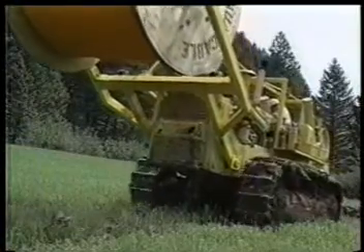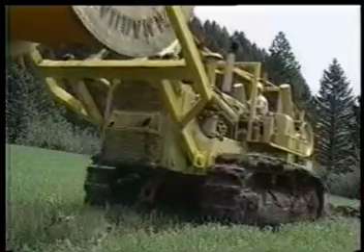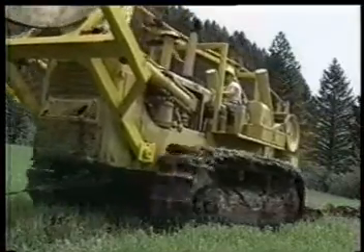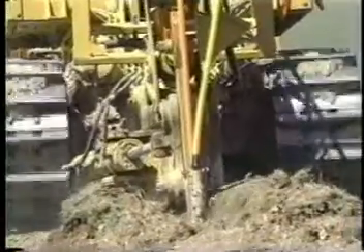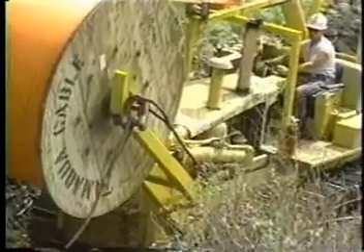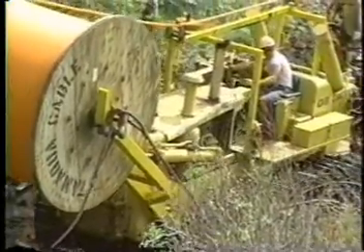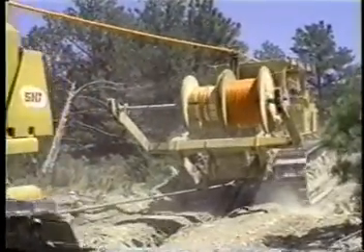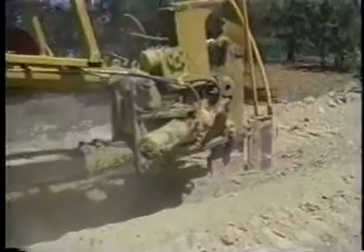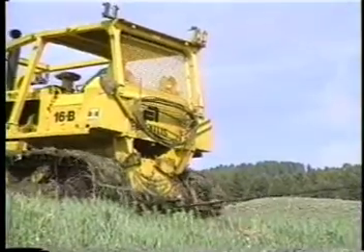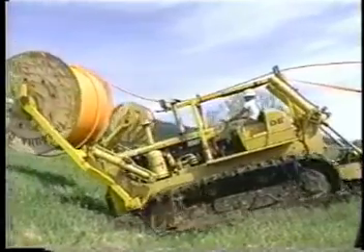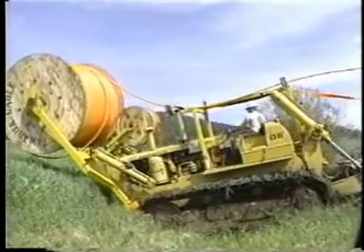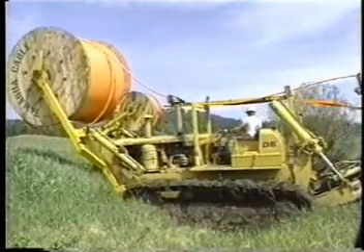When plowing over open land, depth of burial will impact the type of equipment used. For shallow installations under 1 meter, a single cable plow is usually sufficient. Deep installations below 1 meter, or areas of very hard soils, often require the use of an additional caterpillar to provide increased traction. During cable installation, a dynamometer should be used for continuous monitoring of cable tension.